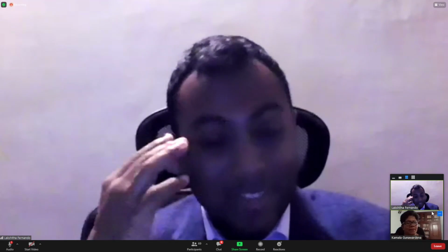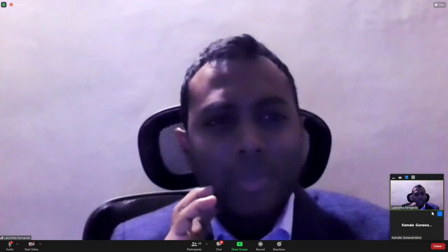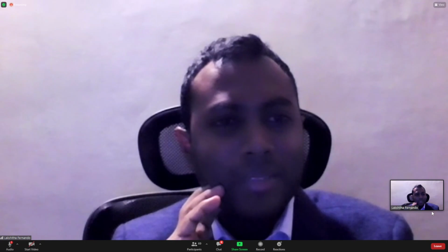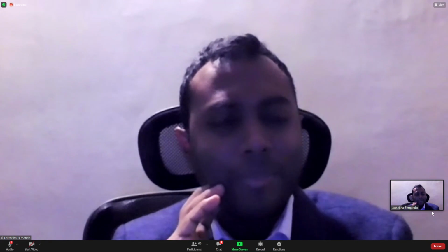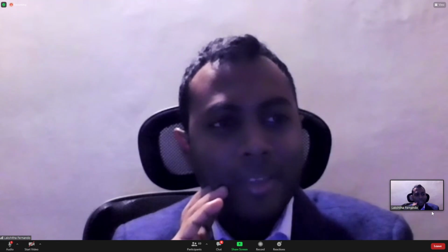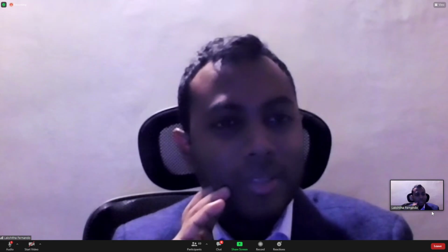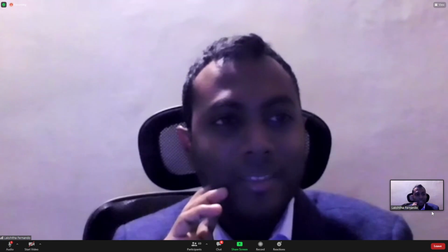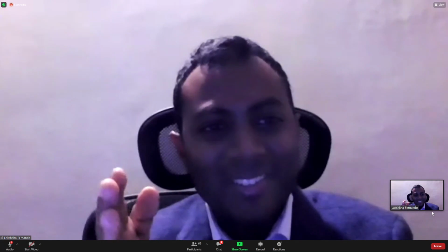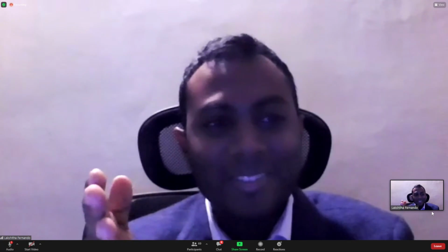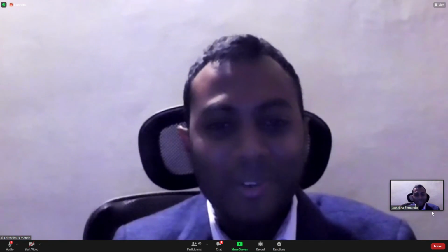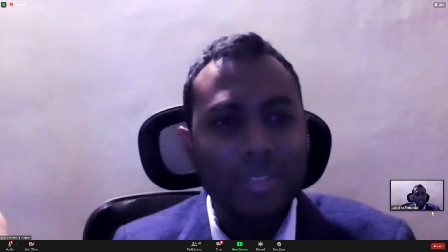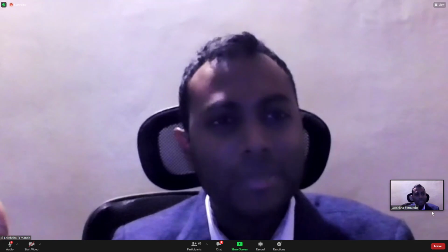Yeah, thanks for the comment. There are two types of dynamic loads, and I think that may be the difference I can highlight. One is impact, the other one is blast. But the way of analyzing both is using wave propagation techniques. So I think that's where you find the common point. With both impact and blast, you have to consider stress wave propagation within the material.